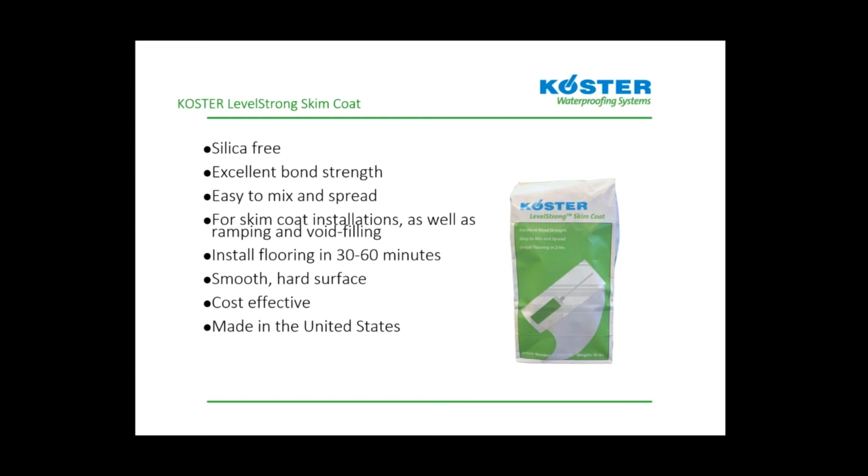Flooring can be installed within 30 to 60 minutes, depending on the environmental conditions. If it's skimmed out, flooring can be installed in as little as 15 minutes. It gives us that smooth, hard surface that we're looking for before we install our resilient flooring system over the moisture mitigation system. Again, this is made here in the US in our facility in Virginia Beach.